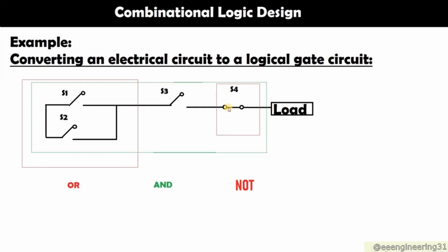Now imagine that we energize this, and this is now an open switch, right? So this is a state of 1. When this switch is open, it's not its normal state, it is its excited state. We have a 1 here, and this is open, meaning we are not conducting any more power, so the output will be 0. So 1 here means 0 here. So this is another proof that this is a NOT gate.